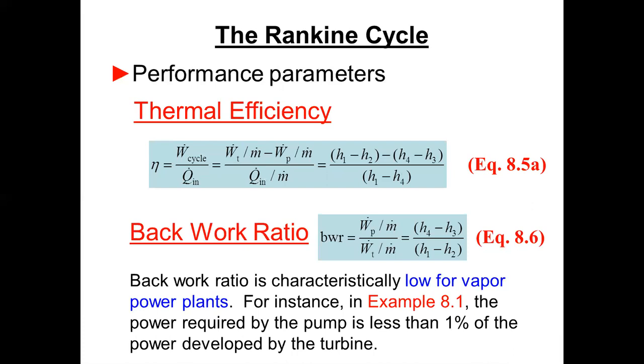And so that's the problem with trying to increase pressure on a vapor. The energy required is tremendous compared to increasing pressure on a liquid like water, which is close to incompressible. You can push pretty hard and you don't change the density much, but you start pushing on air or gas or a vapor, and you have to push really hard, and you get a lot of heat as well as an increase in pressure. So it's just not very efficient to compress a gas compared to pumping a liquid in a cycle.